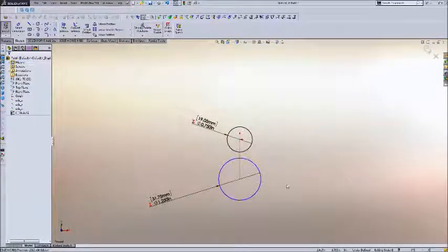I just set those two tangent and I'd be done. The reason I don't do that, however, is because gears aren't always made perfectly. We like them to be, but they're not. So sometimes they're a little slop, sometimes there's manufacturing tolerances. Sometimes you just need to wear in.